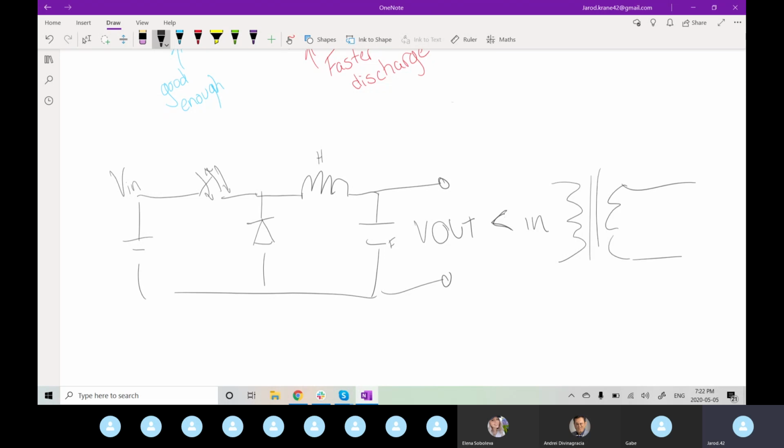If we wanted our output to be isolated from something else in our system, we want our coils to de-energize completely before we're switching on and off. Since this happens at multiple kilohertz and above, it's a fast switching frequency to be able to regulate your output voltage. In that case, you may need your coils on the output to discharge fast enough.